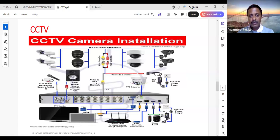Different types of cameras we have, and we need a power cable. As you can see, this is a 120 or 220 volt power supply, I mean the normal AC power supply. But what is the output? As you can see over here, it's 12 volt DC. So here is the input: the input would be just 230 volt AC, but the output would be 12 volt DC. So with the help of this adapter, like what we normally use for our laptop chargers, mobile phones, etc., similar to that, an SMPS we can say.